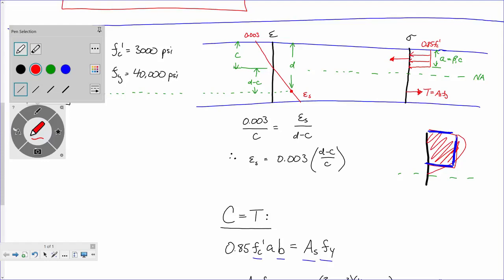Not like that, right? If this is my stress block, and it's like a distributed load, then the middle of it is about halfway down. Can you all tell me, just looking at my stress block, how far is it from there to there? Because remember, it's a moment. I need force times distance.